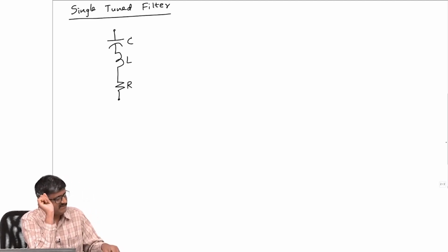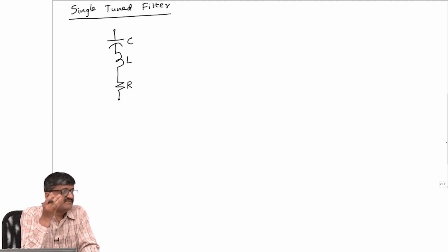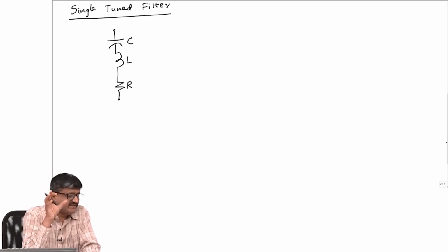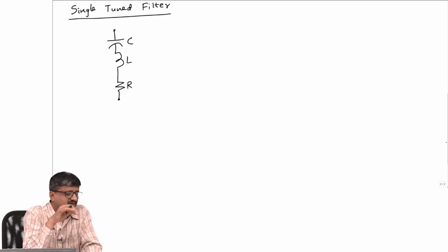That is more because of aging, as time passes, and also the change in temperature. Capacitance is dependent on temperature. The temperature can be due to two reasons: the ambient temperature itself, which has nothing to do with what is going on in the capacitor, or due to the heat produced in the capacitor itself. That also decides the temperature.